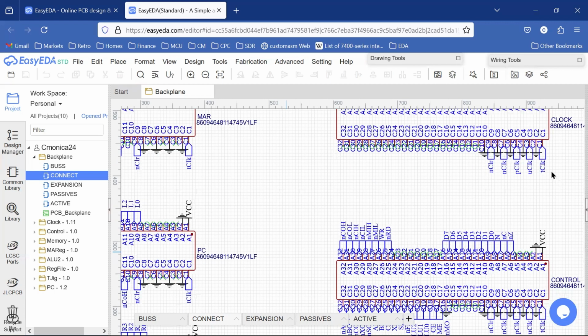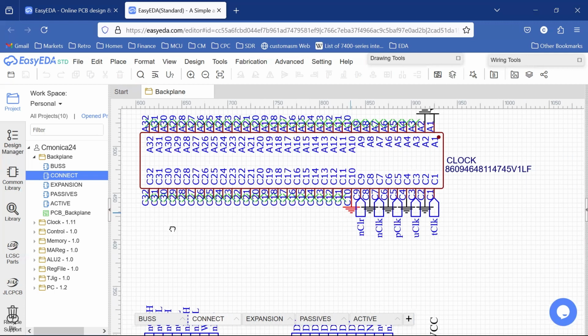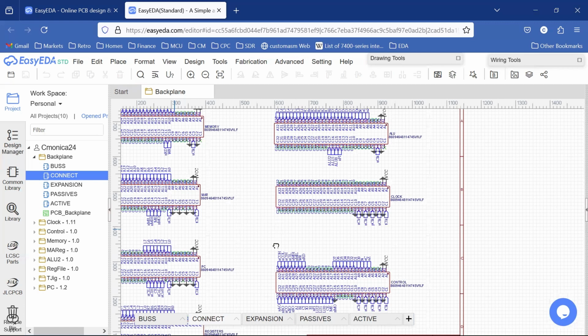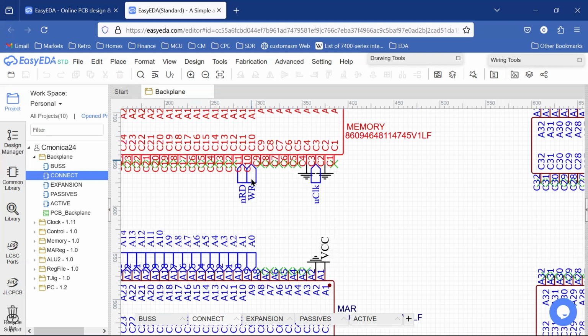So if you see here, C10 should be a ground connection. And somewhere along the way, I made an error and I started using C10 as a pin for signals. And that technically is an error. It should have been ground line on every card edge connector.